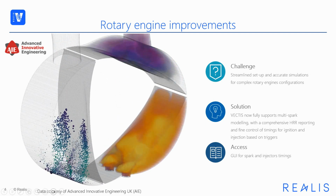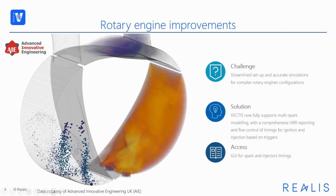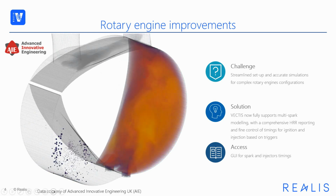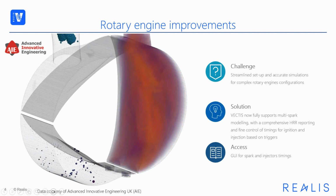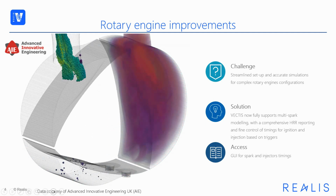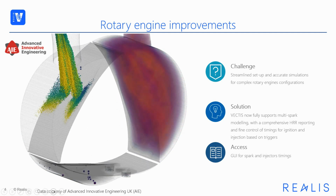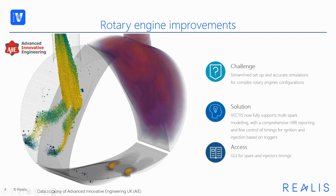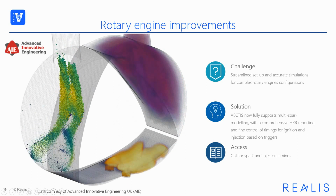With this new release, VECTIS makes innovation in UAV propulsion accessible by allowing even more accurate simulation with a streamlined setup process. The key enhancements unlocking innovations are an advanced ignition strategy support to accurately simulate intricate ignition strategies for which the local conditions may lead to very different kernel development histories. We have also added a fine control of timings based on triggers, offering an easier configuration and greater flexibility in setting up complex injections and ignition strategies.